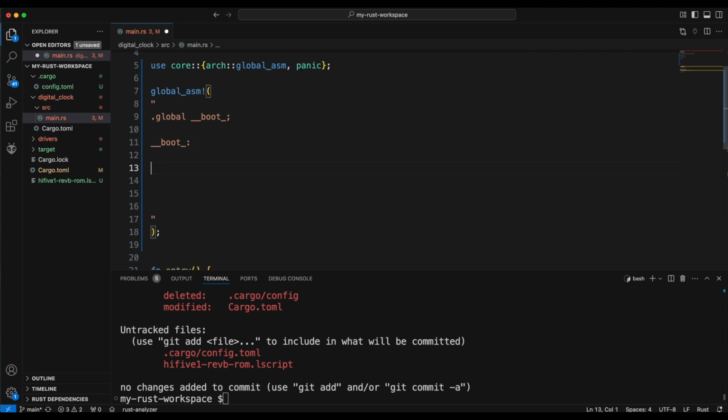Two things to do very first. Let's disable the machine external interrupt, because when we are setting the boot code, we do not want any external interrupt to interrupt this boot code flow. And the second one is to set the stack pointer.